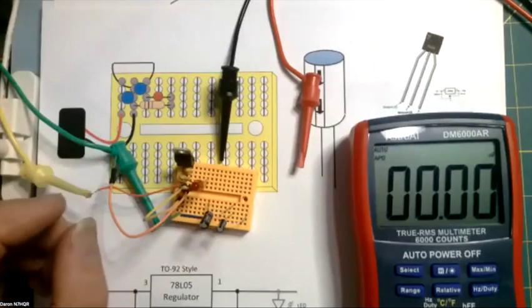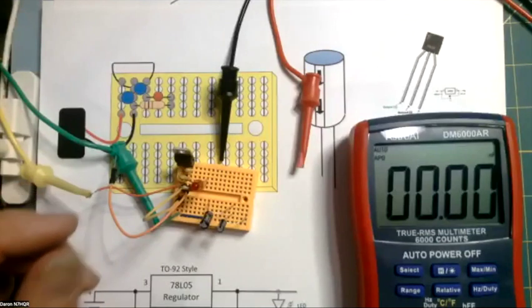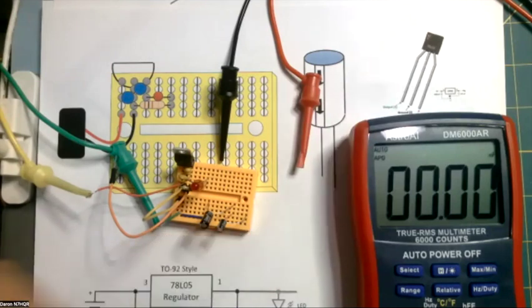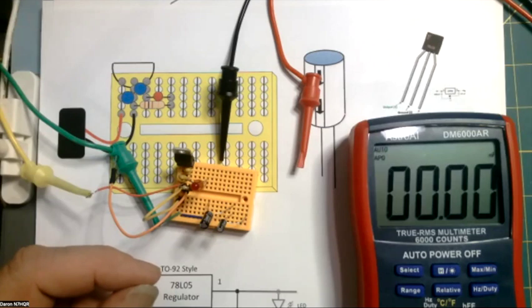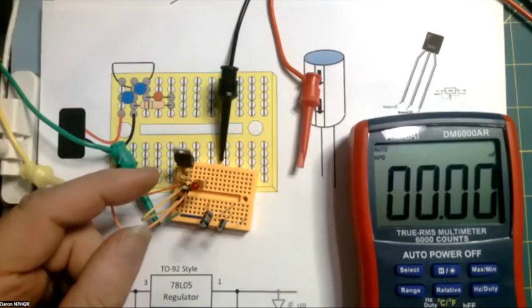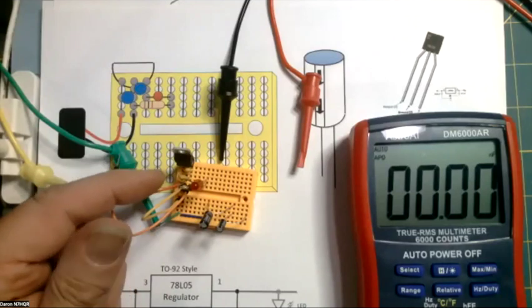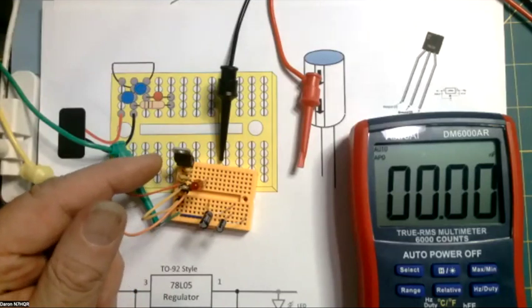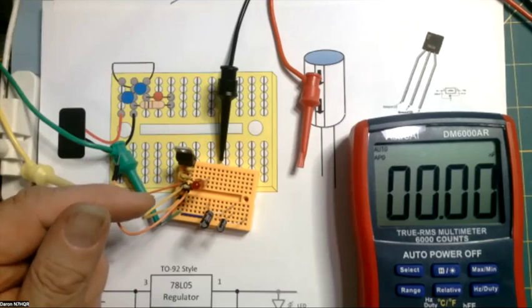Yes, so the confusing thing about this is how they are connected. Whether the circuit goes through the capacitor, or whether the capacitor is connected to ground. In both of these capacitor situations where the regulator is, the capacitor goes from the positive voltage side to ground. So it bypasses.